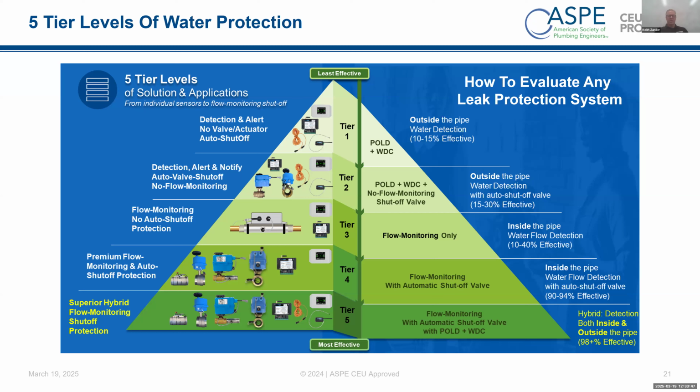You put your video cameras up for theft and vandalism. And they say, you're going to put a leak protection device in there to protect this building. Now, of course, they change the settings throughout the construction process. If I leak water on concrete, not a huge deal. Steel, concrete, but when I start putting my finishes in there, the flooring, the sheetrock, things like that, electrical switch gear, I'm going to want to set those settings tighter.